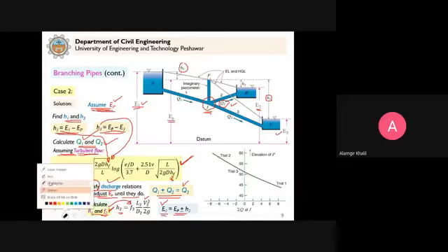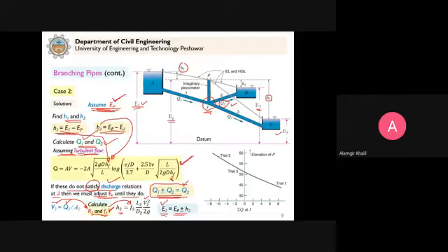So we will have trial and error because we don't know exactly the position of EP at first. If initially we can guess the correct position of EP, then in the first trial we will get the solution. Clear? Because we have to justify this condition here. So in this case Q2 is given, but Q1 and Q3 come because we assume the value of this EP.